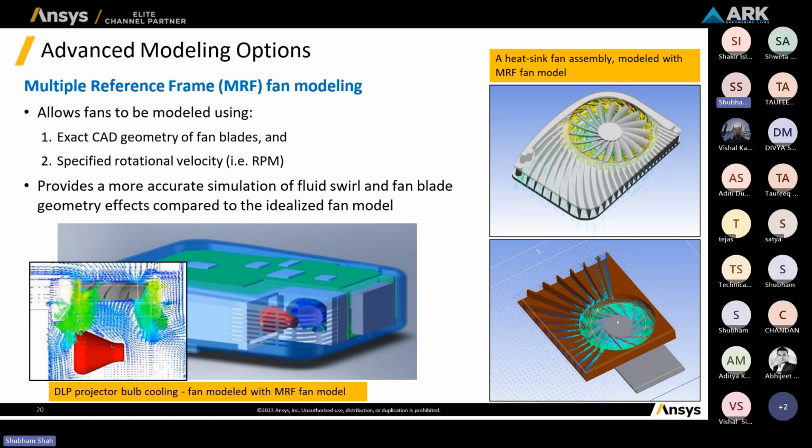The region defined as MRF will act as a rotating component. So you can reduce your modeling time and simulation time with the help of MRF fans, and you can get results as accurate as transient simulation results. You can also analyze the flow swirl and the fan effects on the fan blade geometry due to your wind pressure.